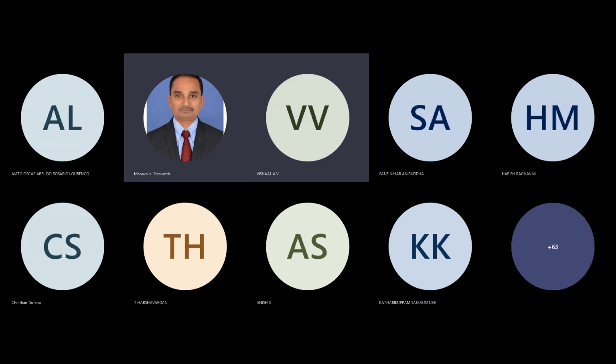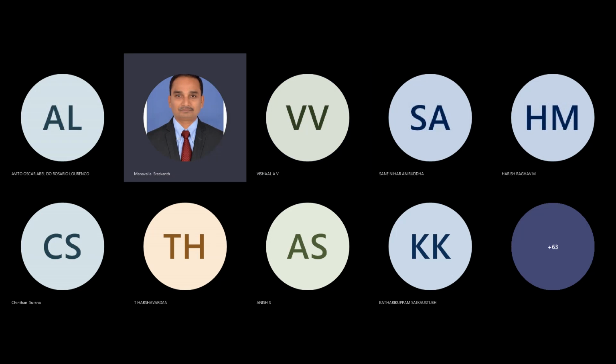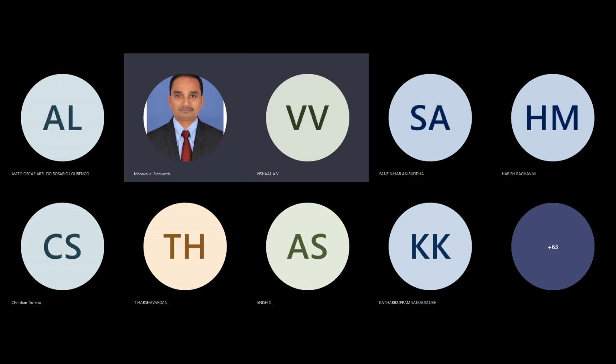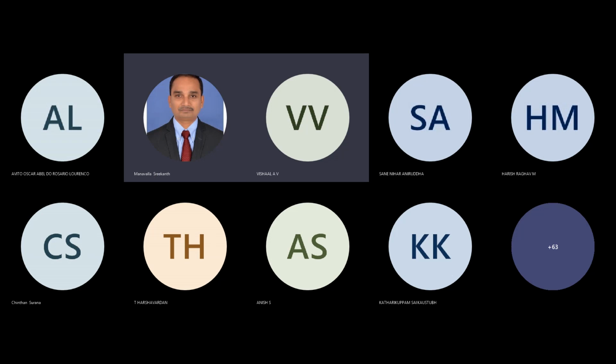Okay, so let me create a new slide here. All right, so I will take up a problem and solve it. Look at the problem, we'll read it. The wall of an industrial furnace is constructed from 0.15 meter thick fire clay brick having a thermal conductivity of 1.7 watt per meter Kelvin. Measurements made during steady state operation reveal temperatures of 1400 and 1150 Kelvin at the inner and outer surfaces respectively.